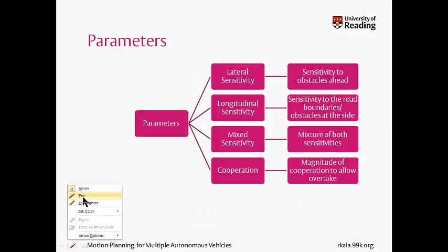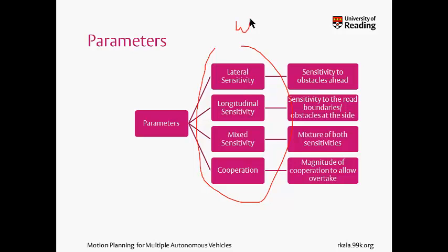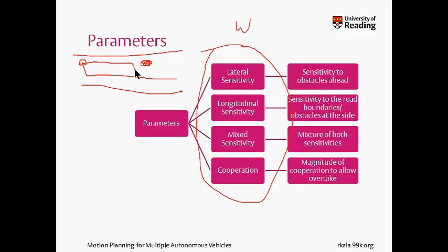And if I am adding potentials from different sources by different weights, those weights out here will be my parameters. Now what do these parameters do? There is one parameter which says how scared you are of the obstacle. So if you're very scared, you'll immediately turn and then travel straight. If you're not at all scared, you will travel like this and then you will take a sharp turn and then again go straight, and there's something in between.